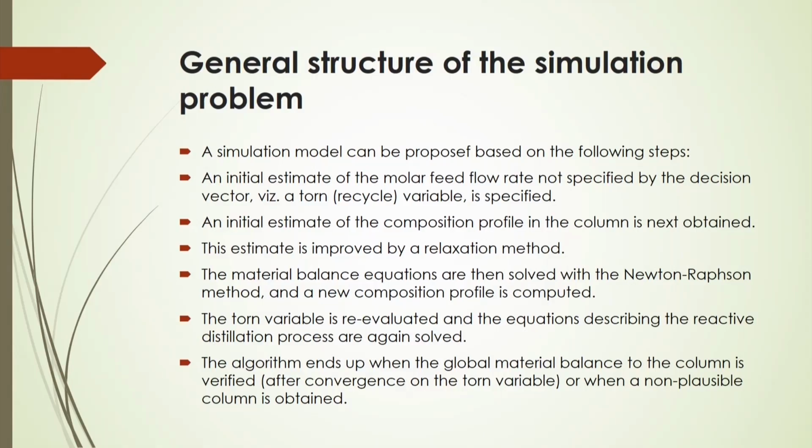The equations describing the reactive distillation process are again to be solved, and the algorithm ends when the global material balance of the column is verified after convergence on the tear variable, or when a non-plausible column is obtained.